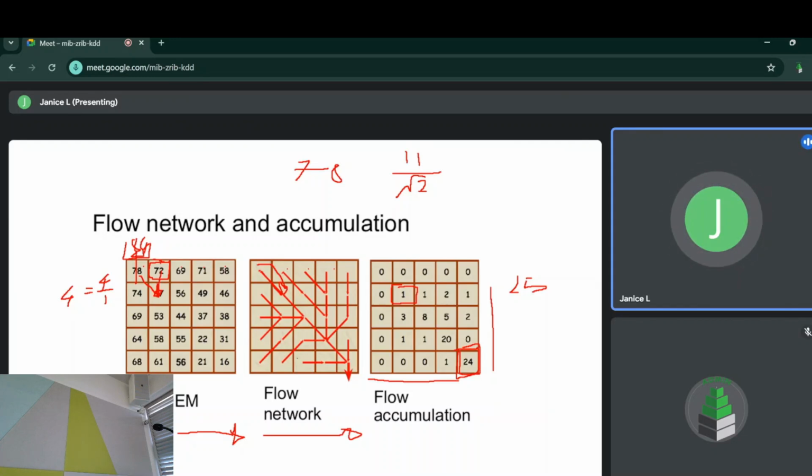And then if you actually have proper software to do it, it gets a lot more detailed, it gets a lot more complicated. There's a lot more data points to work with than our humble 5 by 5 grid. All right? Yep, and that's what you do. You identify the outlets, and then you have these catchments by following the streams in reverse order, and then you have it. These are your catchments.